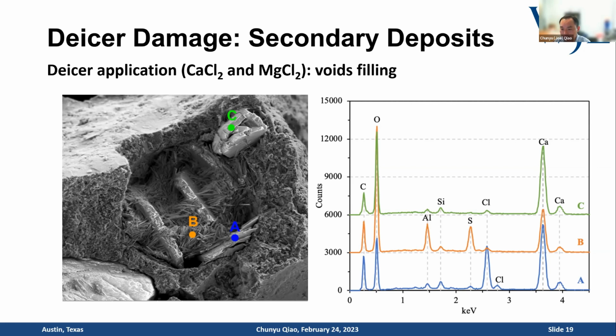So like I said, if you have water reducers, especially for SCCs, as a special application, you use all the different kinds of admixture: shrinkage reducing, viscosity modifier, water reducer, or slump changer. All those things will change the early age performance or behavior. It is more about rheology, and the first few days, the hardening, the setting, all those things that I said. If we're looking at early age concrete with different extended hydration, that goes to different hydration degrees, right?